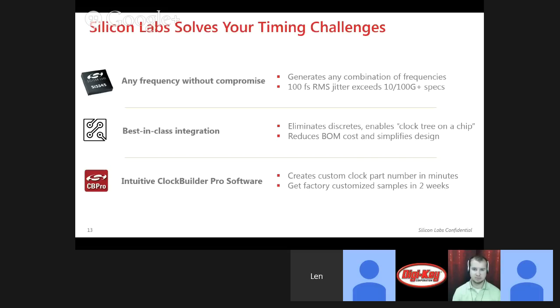And maybe you don't need really low phase noise, but it's nice to have that margin and know that you have a really good quality clock, especially if you need to make changes. Integration, really, folks just want more clock outputs, and these have up to 10 differential outputs or 20 CMOS outputs. So that really enables you to get that 10, 15, or even 5 part BOM count down to maybe just a couple of parts. So you need a lot of flexibility internally on the chip and then lots of outputs.